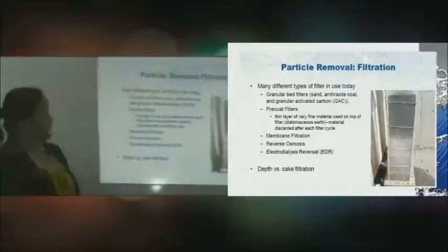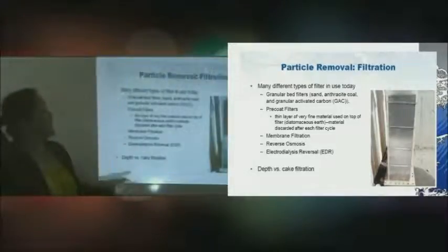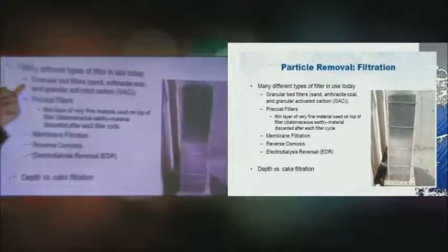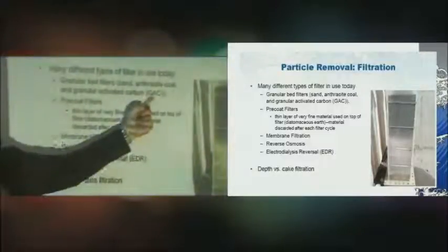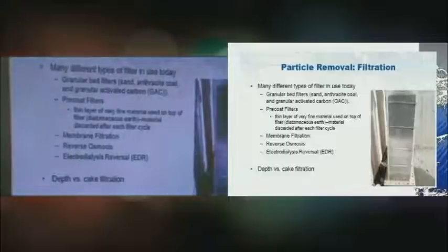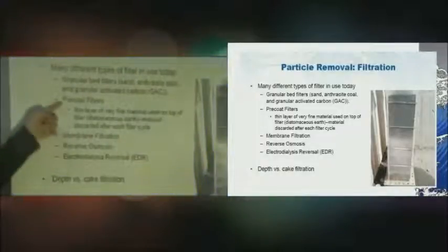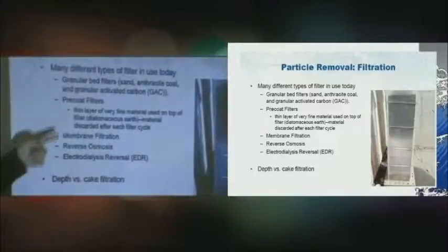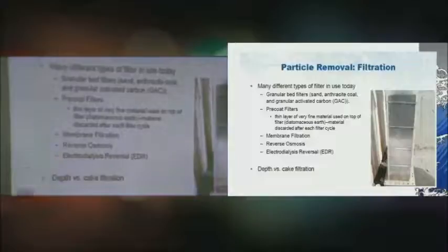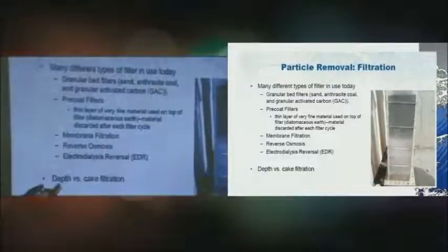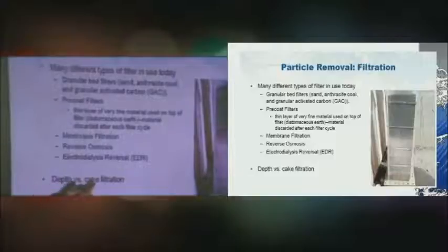So there are many types of filter. You may have the granular bed filters. You have the granular activated carbon, which is normally utilized if you have problems on odor and taste. Then you have the pre-coat filters. Then you have membrane filtration, reverse osmosis, electrodialysis. And here for the filtration, what matters is your design of the depth versus the cake filtration.